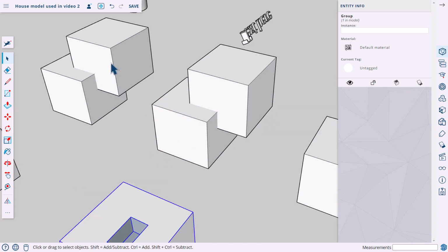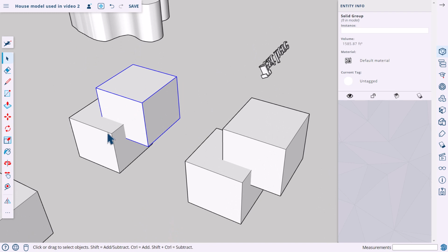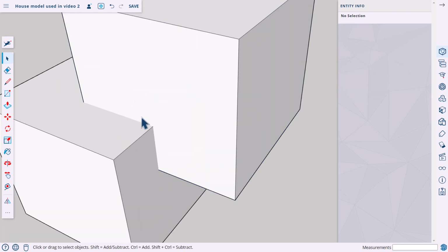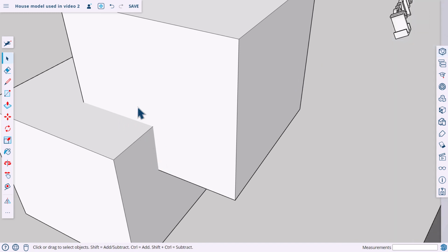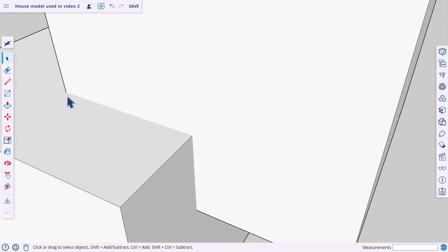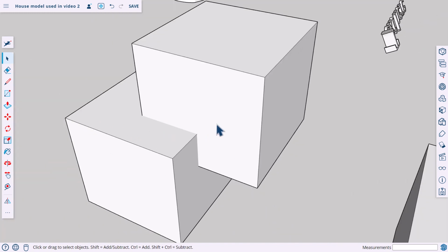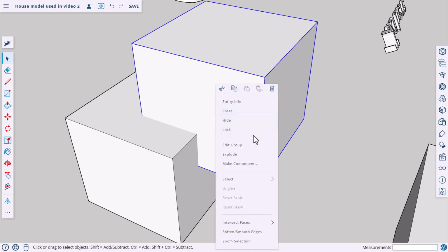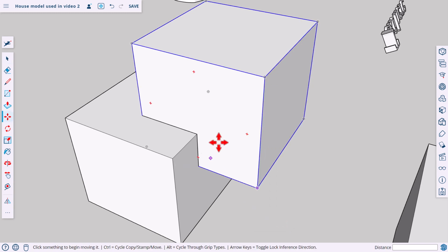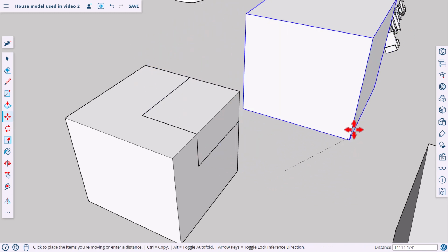I have to use these objects. And both of these are solids. And one thing, when SketchUp overlaps objects that do not stick to each other, you will see that there's no line there between the two of them. If you have some reason that you want there to be a line, the most basic way these objects interact is you can intersect these objects with the model. Just right-click on them and choose intersect with model, and you'll see the lines pop up. And we're not even messing with the geometry, and this will work with non-solid objects.